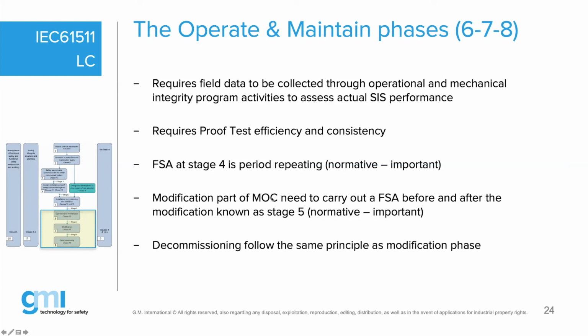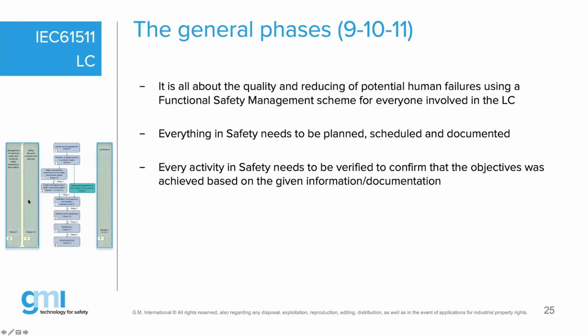Modification, typically known as the MOC, that's your management of change, needs to be carried out, and the FSA before and after your modification is taking place. Now, to summarize the general parts, the management of functional safety, I would recommend going back to the webinar on YouTube on functional safety management. There are some key issues. Even when you have all your SIL documents correct, you have all your calculations correct, or even all the certificates, you still do not comply with anything without proving functional safety management for any product supplier and for any service supplier. That means any system integrator or maintenance service or whatever service you supply in the life cycle phases, you shall have a functional safety management in place and prove you are using it. It doesn't make sense to have a quality procedure if you don't use it. You have to prove that.